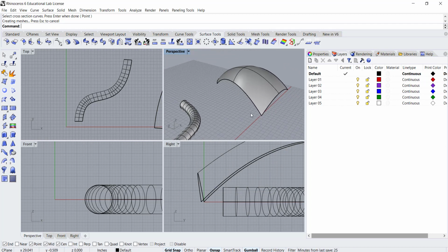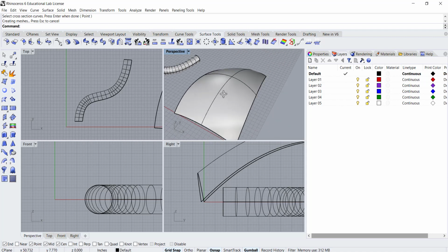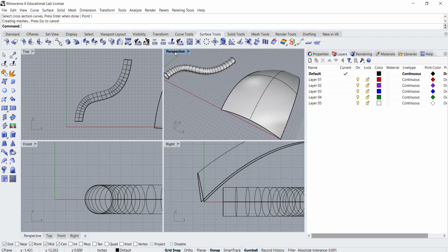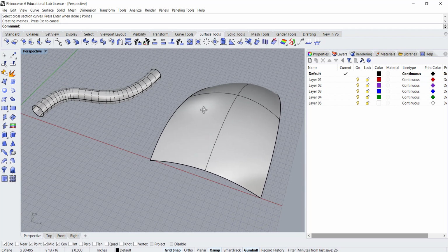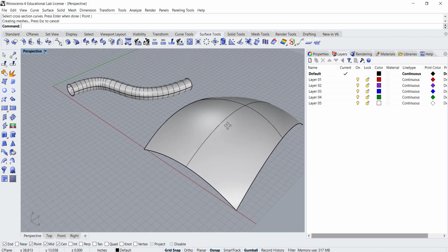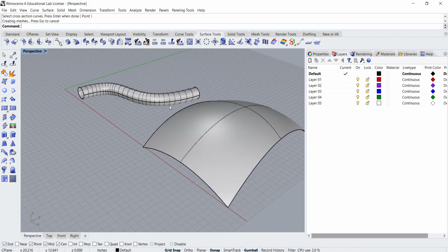And now you can see that we've generated this swept surface. We can see the ISO curves on both of these. In this case, there are a lot more ISO curves on the single swept surface versus this two-rail surface. But translational surfaces, sweeping one and two rails, are really useful ways to work with profile curves and rails.